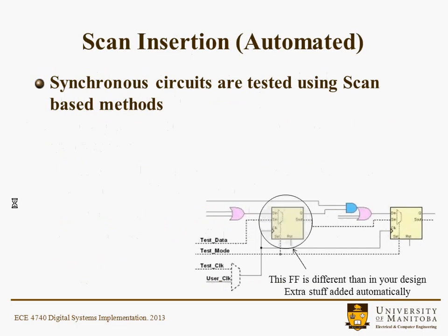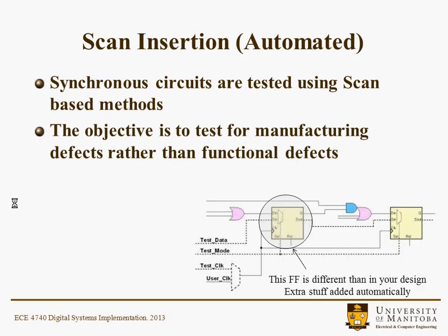The scan insertion is an automated part of the design process, and this is because you typically have some synchronous circuits and you'd like to test them with a scan-based method. What that allows you to do is scan in a test vector, test the combinational logic part of the sequential design, and then capture that again in some flip-flops and then scan them out and observe them. So the objective is to test for manufacturing defects rather than functional ones. So this type of test facility or utility is used once the chip is manufactured.